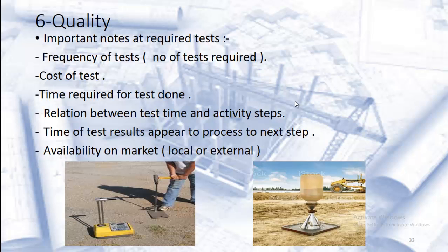Tests like sand cone and field density take a small time to determine and the test results appear. Other tests like bridge loading tests take a long time to prepare. This must be taken into consideration in the schedule of the project. Another item is the time relation between test time and activity steps.